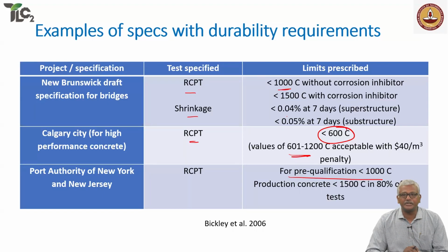For strength determination, what is the typical variability that we expect? When you determine compressive strength, what is the extent of variability? No, that is the design of the concrete for a target strength based upon your characteristic strength. I'm talking about when you test 3 cubes, okay, you are allowed up to 15% difference, but typically when you test cubes, you'll see that your variability is restricted to 5 to 10%, not more than that, right? In strength, the variability is small, but in durability testing, variability can be sometimes as high as 50%. So you need to design your values very carefully.